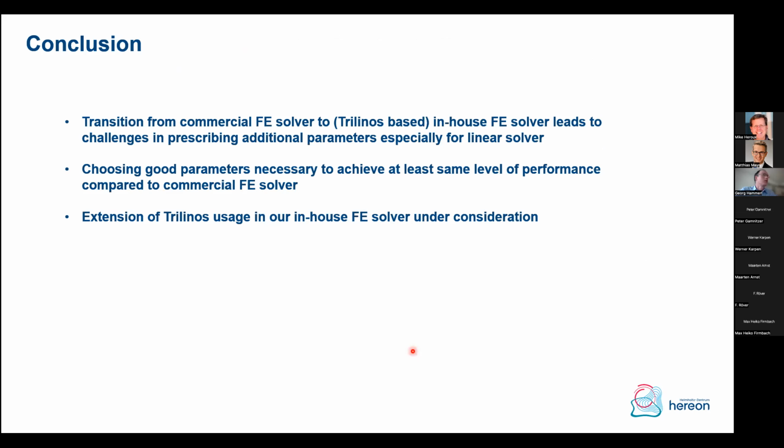So let me conclude. We're currently in a transition phase from the commercial FE solver Abaqus to our in-house solution, which is Trilinos based. This gives, of course, opportunities. We can now tune the solver, which hasn't been possible in the past. But it's also a challenge, especially for those who are experts in the material modeling aspect but not in depth with the mathematical aspects.